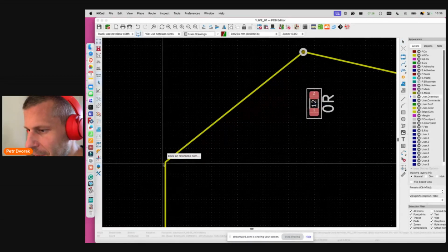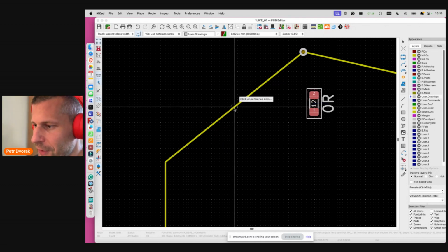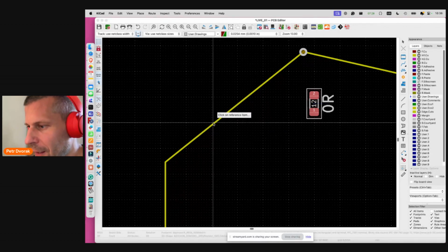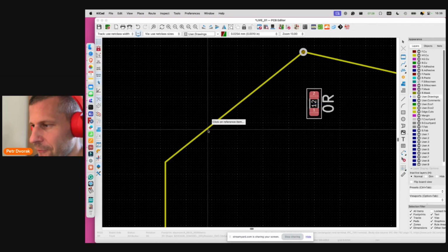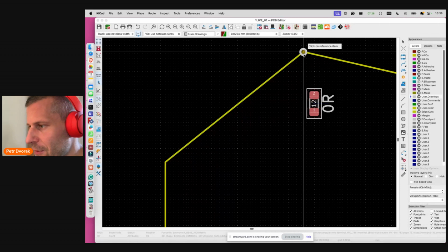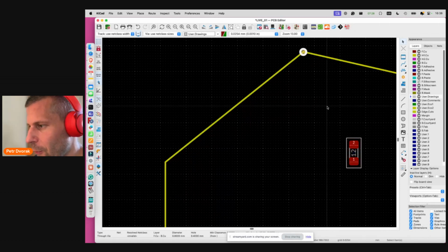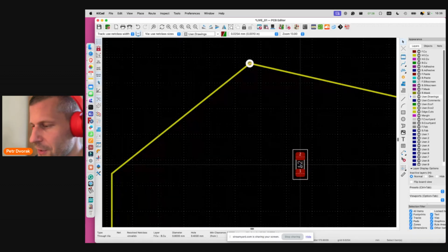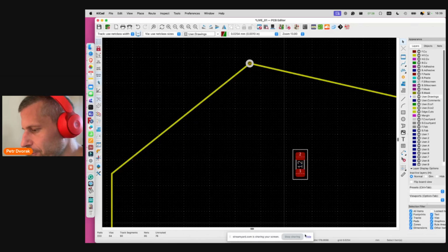If there is a good point, because KiCAD can snap to graphics, but otherwise, for instance, the middle of this line is as well good, but imagine any non-specific place, not endpoints or midpoints. It's hard to anchor. So then there is a via as an object, and by pressing OK, the component is placed. The center of the resistor is in the middle of the footprint, and we can check.